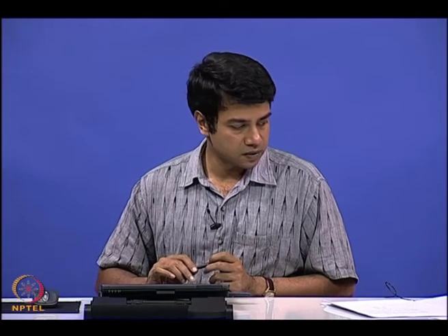When we did the initial lectures, I showed you that the Nusselt number in the case of convection dominated flows at high Peclet number goes as Pe power plus 1/3. We have done here an analytical solution for the flow past a flat surface at high Peclet numbers, and we have got a solution in terms of the similarity variable. I will now use this to show you how we get the high Nusselt number correlations. So, we will first complete the solution of flow past a flat plate in the next lecture, and then I will discuss the flow past a spherical particle and evaluate the Nusselt number correlation in that case.